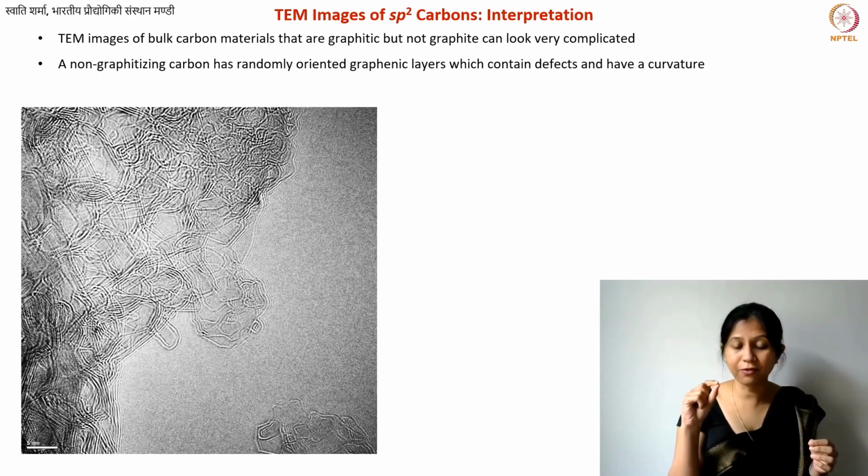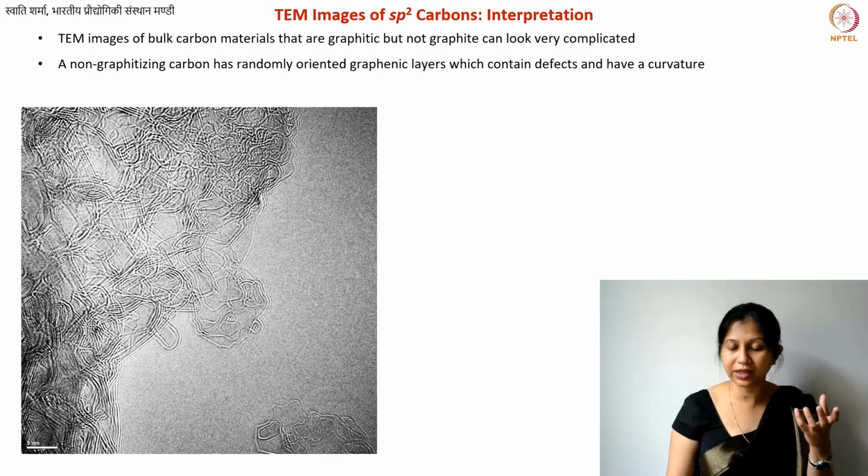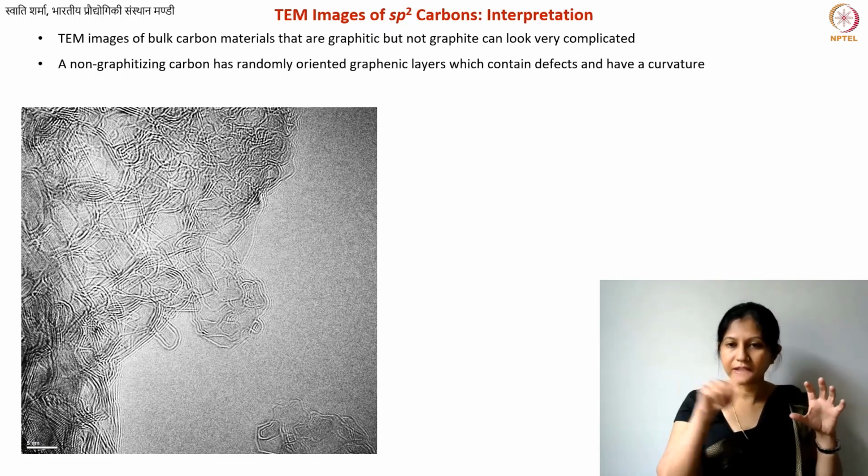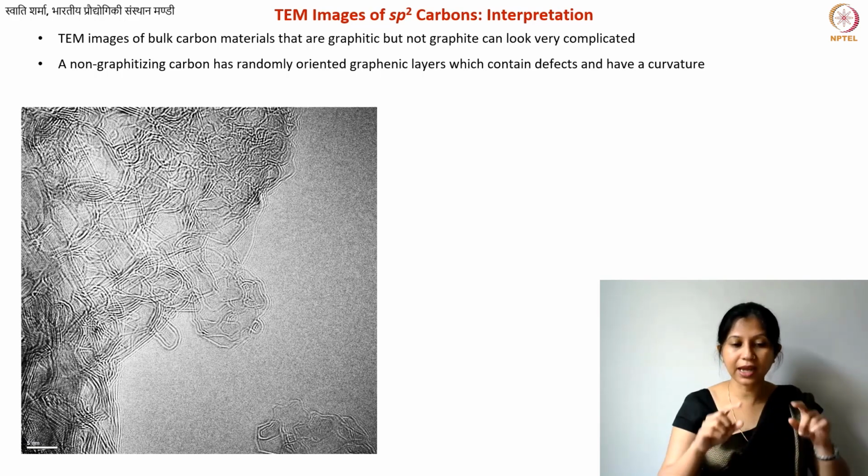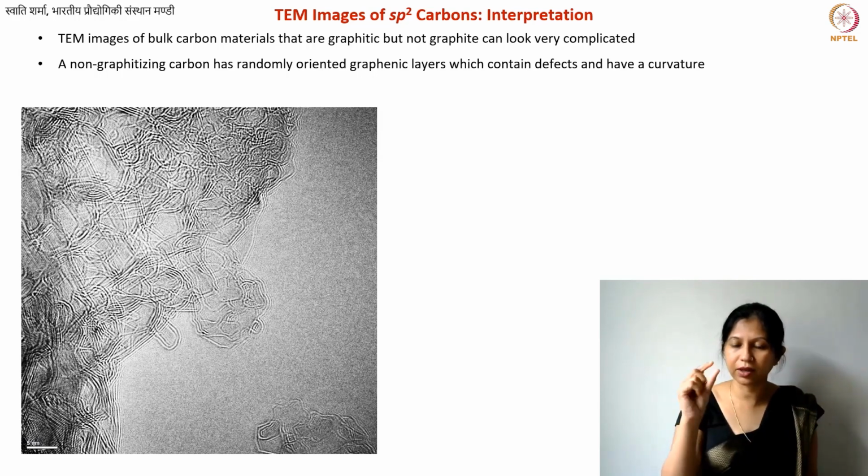But the film itself was extremely thin. When we were taking this particular image, what we did was something known as in situ TEM. In situ TEM means you heat your structure inside the TEM itself using a joule-heated substrate. You can purchase different types of substrates for transmission electron microscopy. Typically, what you use is known as a TEM grid. As the name suggests, it has these kinds of structures. It looks like a net, pretty much, but it is made of metal, and it is circular, about a couple of millimeters in size.